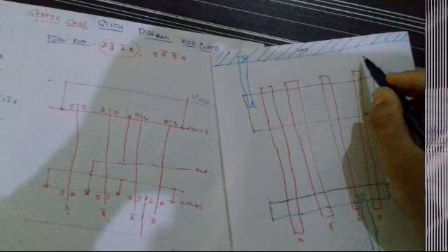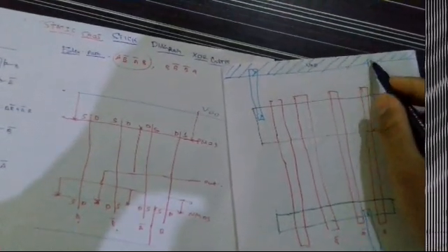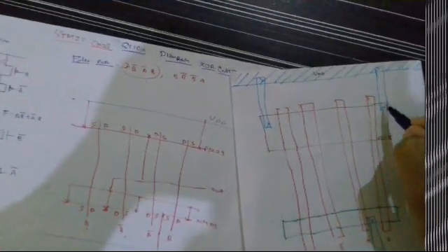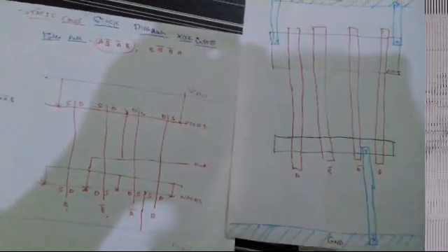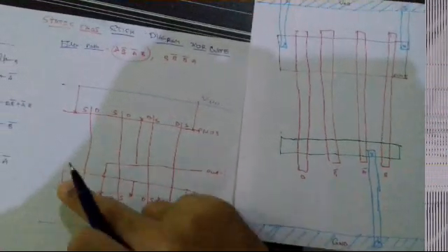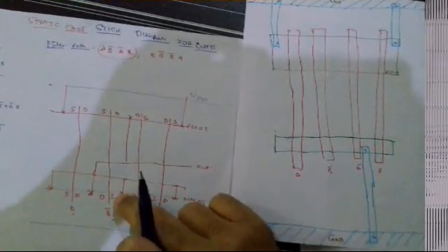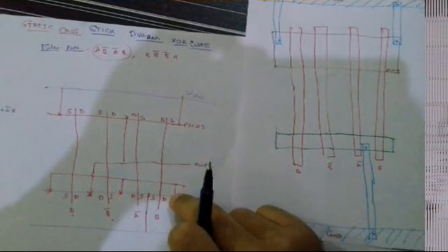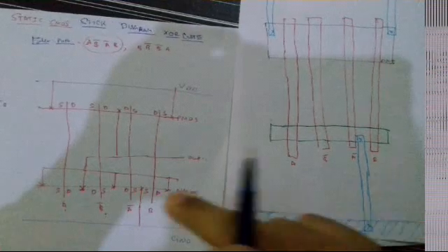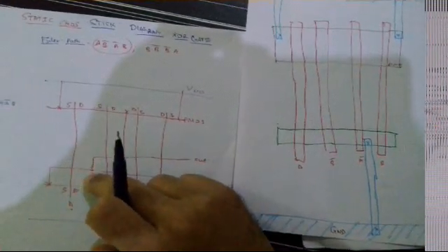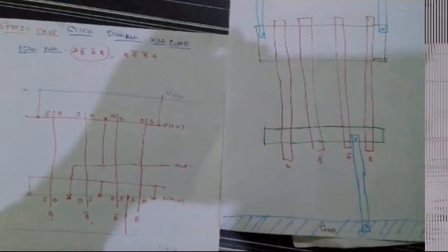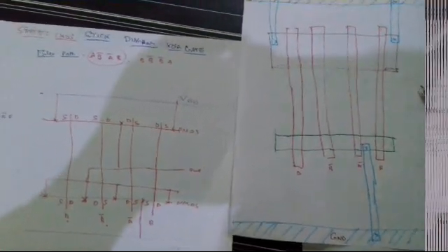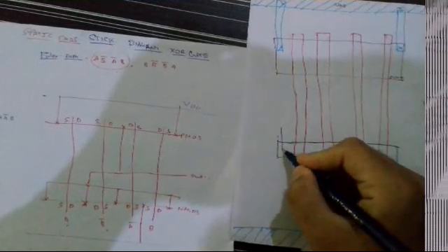So there are certain rules for what the width of this metal and the polysilicon should be, which can be seen in the video which I will provide in the description below. Now we see that this source and this drain are connected, but we will use a metal 2 layer for that because the metal is overlapping here. We also need one connection for the ground. So I will use the purple color for that metal 2 layer as stated in the color conventions.